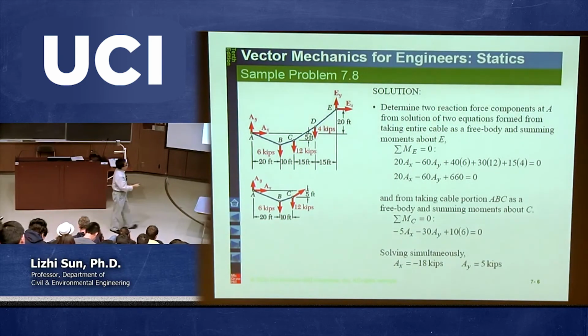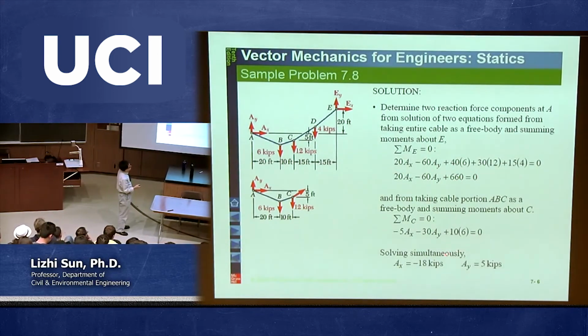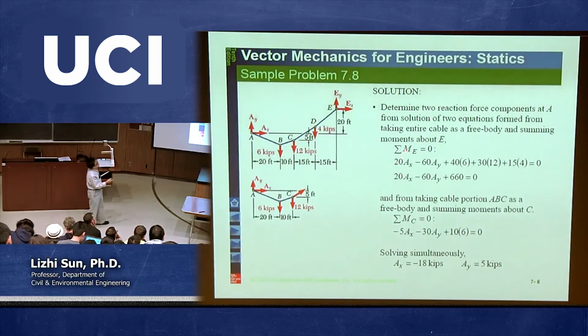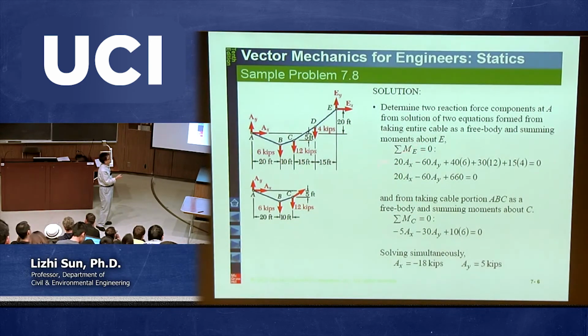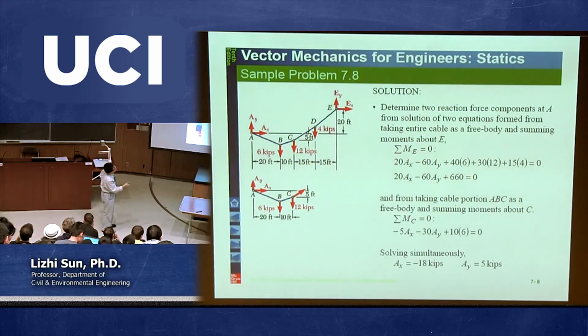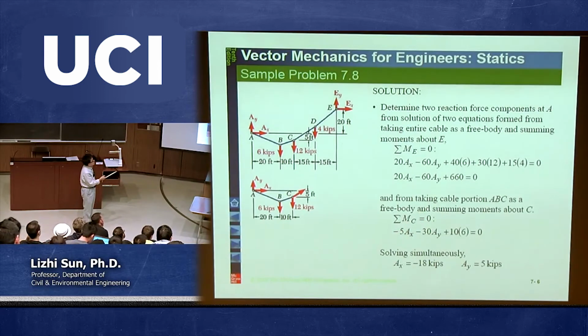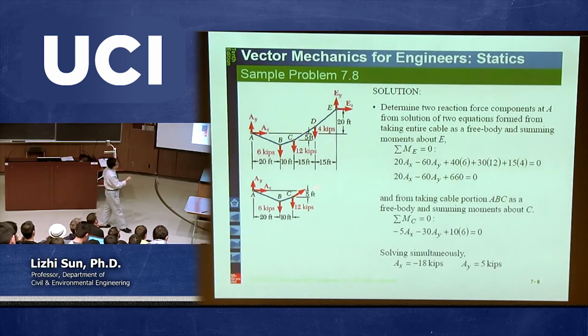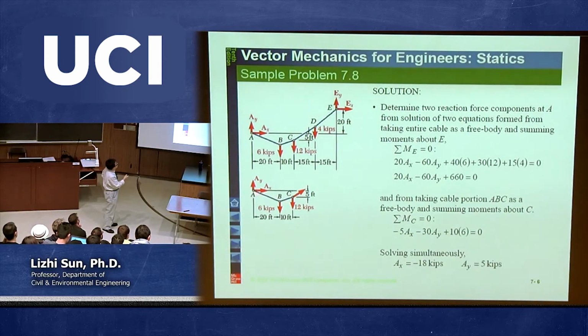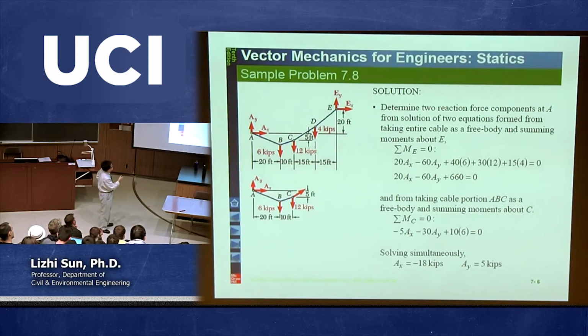So this is what we call a free body diagram of this part. Then what we're going to do is calculate the reactions first. How to calculate reactions? Well, there are many ways because you have three equations anyway. You can use whatever you like. Let's take a moment at point C of this structure. These two forces will not be involved. That's fine. But you have Ax. So Ax times the shorter distance from here to here, Ax times 5. And this is going to be clockwise on this rigid body, right? So that's negative. So this is the moment due to Ax.